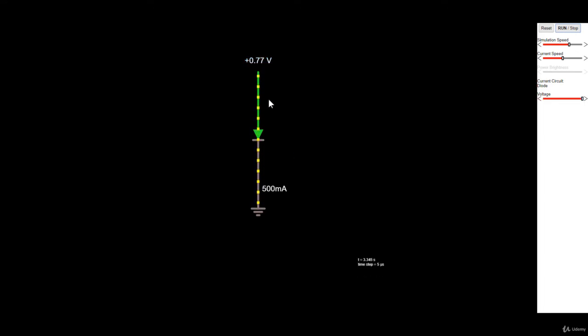Now what happens if we reverse bias the diode? The voltage is negative 1 volt, and you can see that the diode has very high resistance right now and doesn't allow the current to pass through it. You would have to increase this to a relatively high value until you pass the reverse breakdown voltage, but once you cross the limit, the diode will be destroyed and it will allow the current to pass through even in the reverse direction.